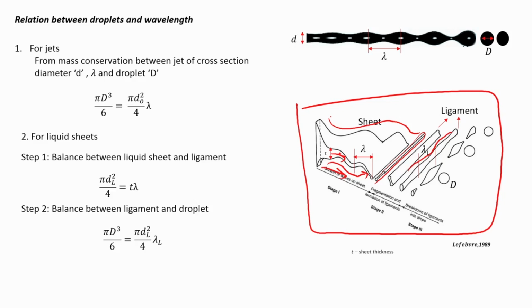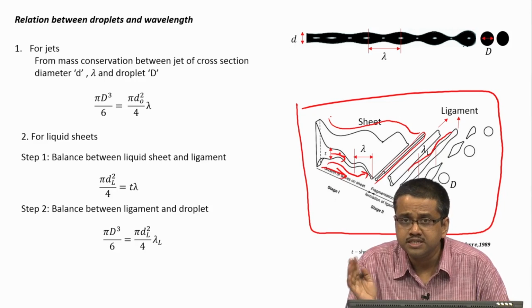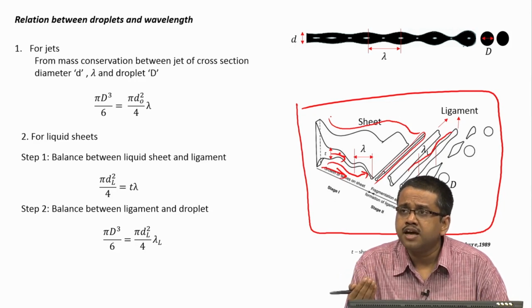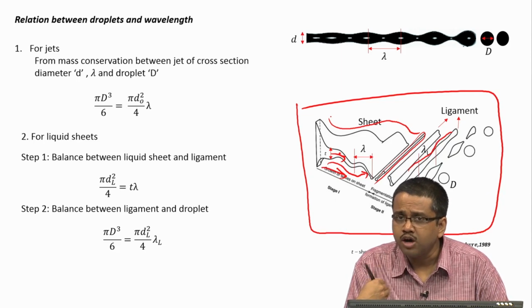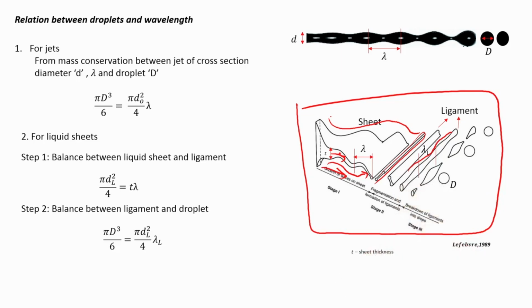So, there is a common misnomer that, oh, I know what droplet sizes are coming out of the nozzle. That is incorrect, right. In order to predict what droplet sizes are coming out of the nozzle, okay, or after a certain distance away from the nozzle, right, one needs to actually know the atomization mechanism, so to say.